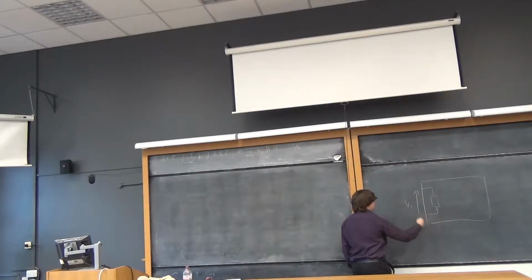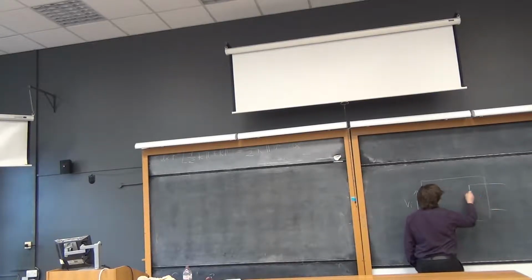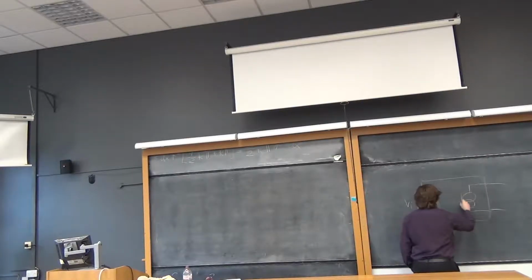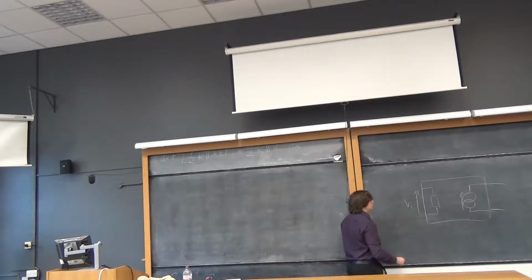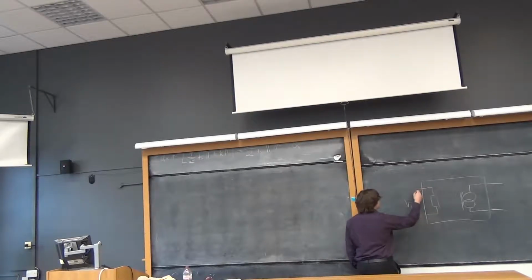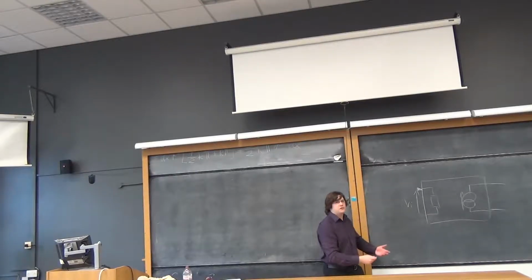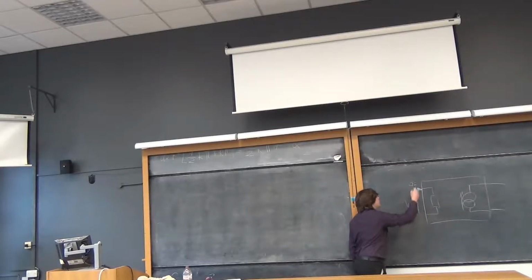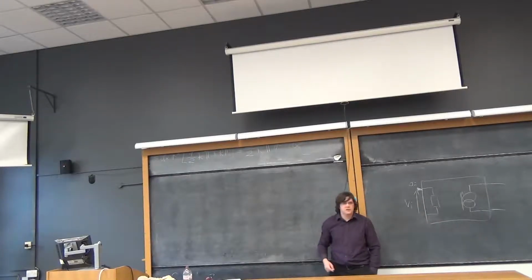We'll say it's voltage input for the sake of argument, and also for the sake of argument we'll say it's current output, because that would probably make it a bipolar transistor. So if I wanted to know what the value of this input resistance was, I could measure the amount of current that's flowing into this node by breaking the circuit and putting an ammeter in there if we're actually physically doing it. And if I divide VI by I in, then I'll get the value for whatever R in is. So that's input resistance.